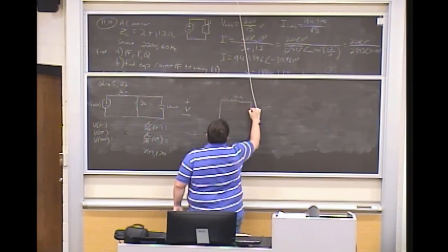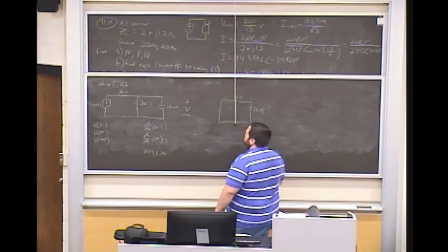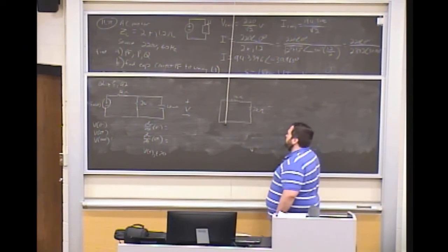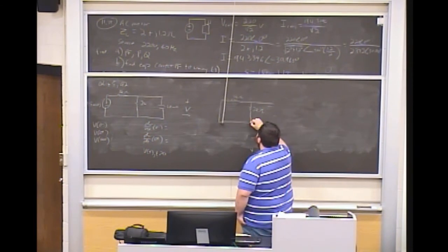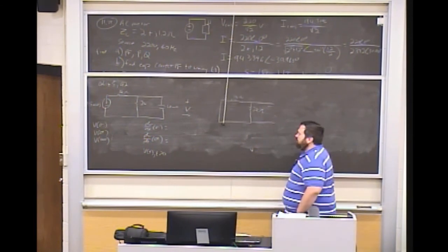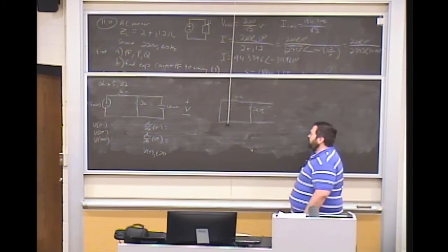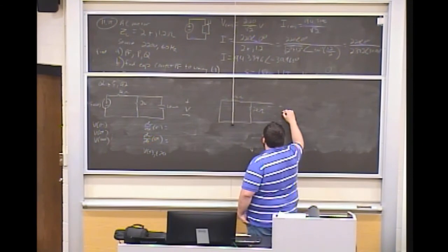Resistors just kind of hang out and do their thing. They're pretty resilient. They can change current instantly. They can change voltage instantly. What does our capacitor behave like? Open circuit. All right, so at 0 minus, what's our voltage here? 0 volts.